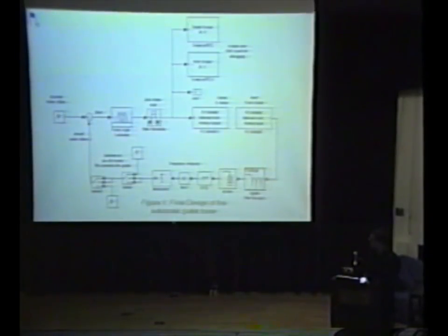These switches here are just for protection of the guitar. The first switch is if the string gets turned too high, then the motor will turn off so the string doesn't break or damage happen to the guitar. The other switch is so that if the guitar gets tuned too low, it'll turn off the motor, because the harmonics of the note will start to go through the filter and it may try to tune to one of the harmonics.